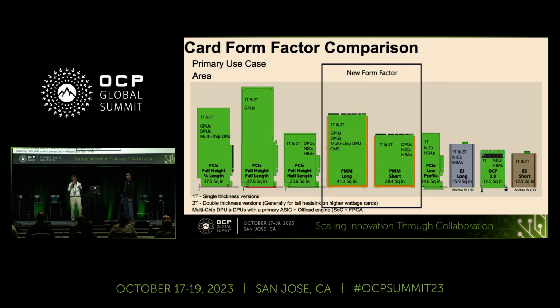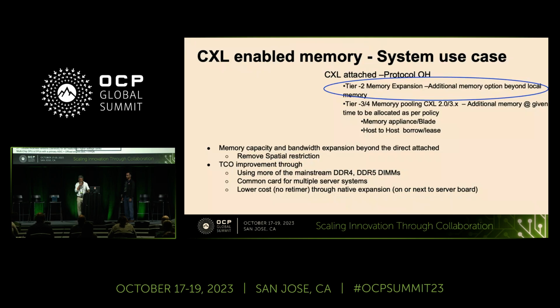So this is the card form factor comparison. If you look at, these are the new form factors which we are basically introducing in between. The PCI will remain. The E3 will remain for their own thing, but the biggest advantage of this one is that you can use standard RDIMMs, and it's a pluggable form factor, provided we write software which will allow you to dynamically add and remove the memory and all other things. Hardware-wise, everything is designed for that.